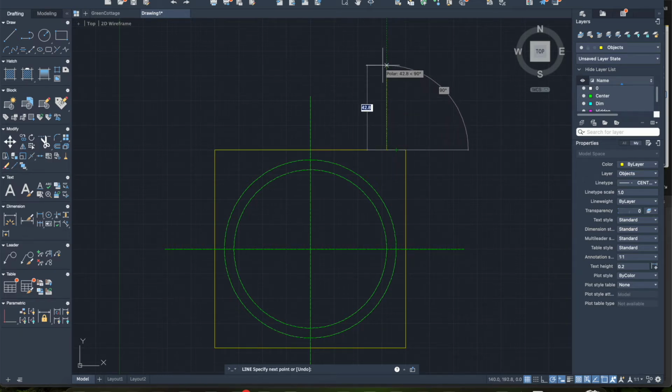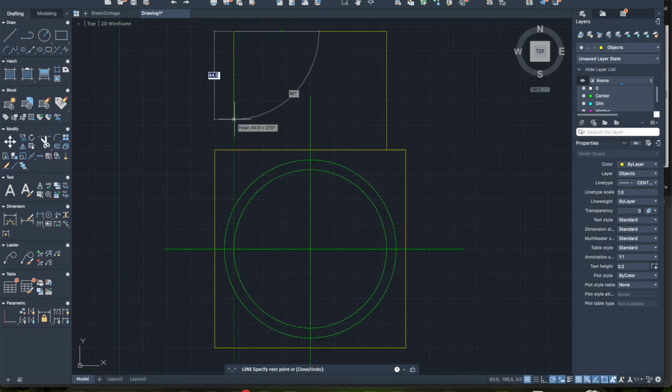And then if you look at the drawing, it's 60 millimeters in height. So you put in 60. And 40 plus 40 gives you 80. And then you just complete it with 60 and you hit spacebar to trim it.